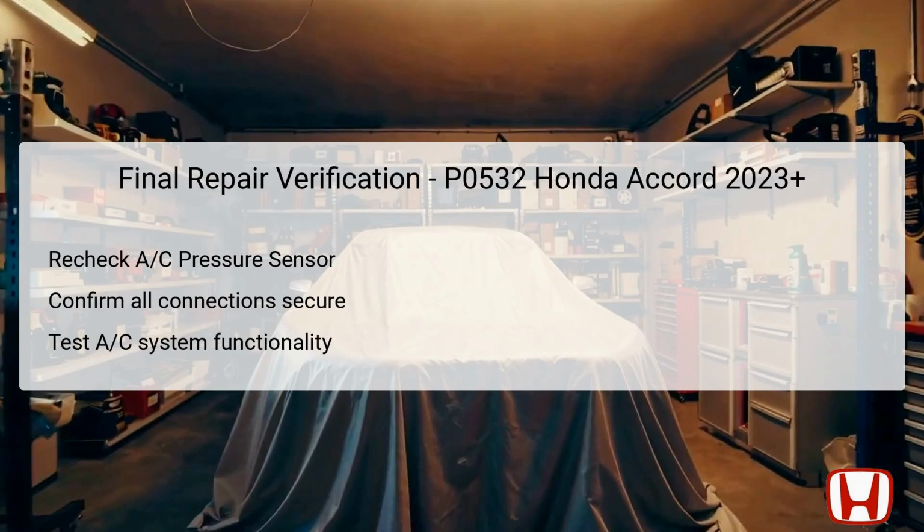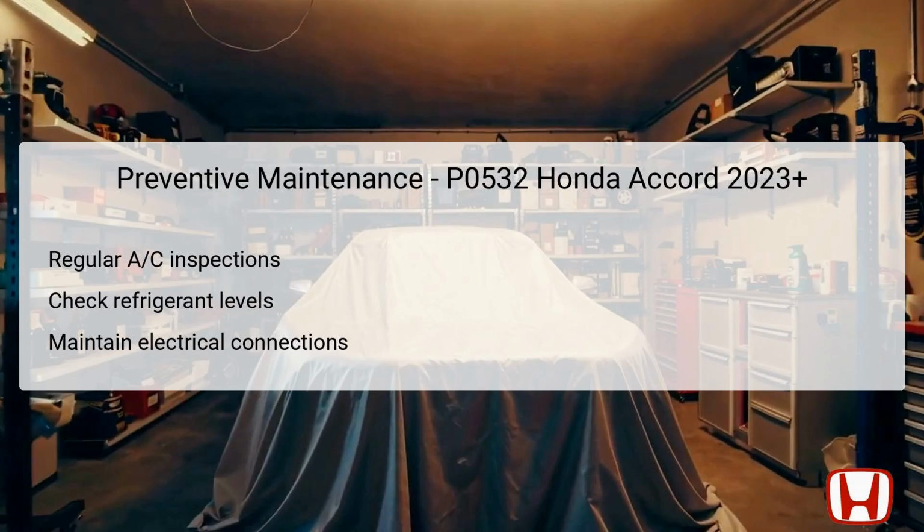Following this, test the entire AC system to confirm that it is operating normally and that the cooling functionality has been restored. Monitor the system's performance to see if any DTCs are re-registered during or after the test. This final validation is vital to guaranteeing the repair's success and making sure the AC operates effectively in the long run.